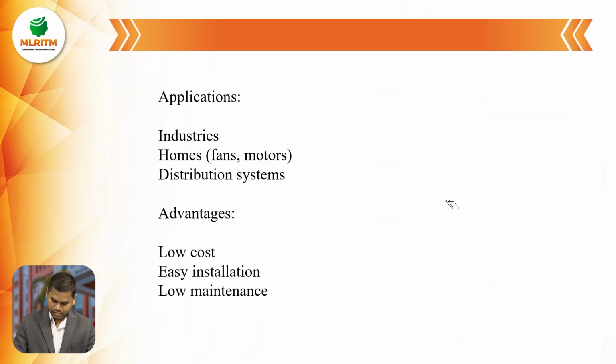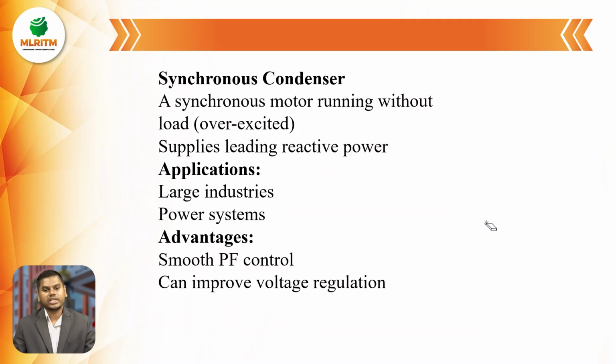Okay, next, synchronous condenser. A synchronous condenser is a synchronous motor running without load, without mechanical load, and it is over excited, so it supplies leading reactive power. So that is the purpose of the synchronous condenser.